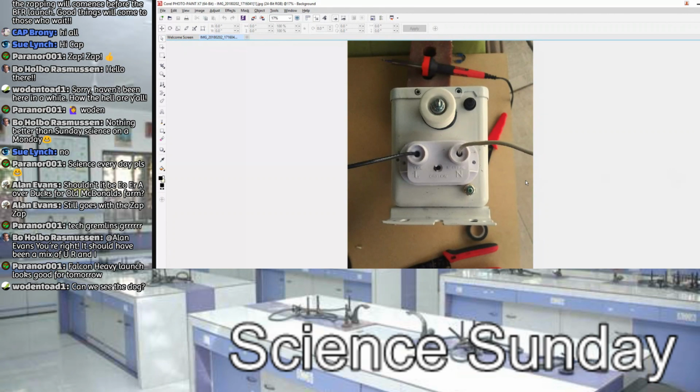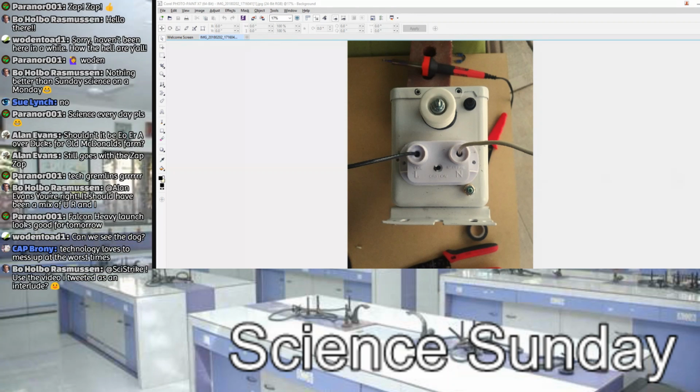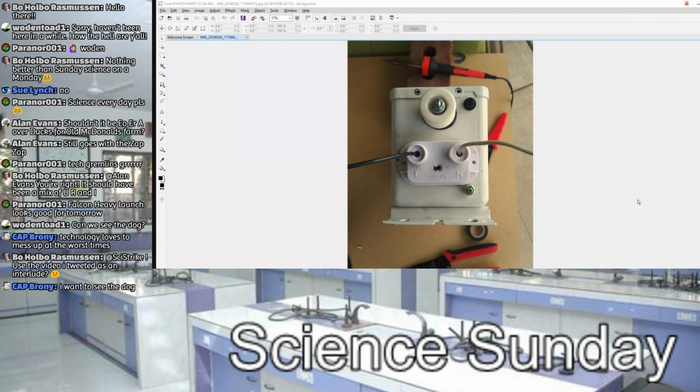So under this fancy little cap with this nice little charred thing you can see there is the ground fault interrupt circuit that neon sign transformers kind of have to be built with these days. And you can see from the char, I blew up the LED with a little bit of a feedback surge, so I went ahead and pulled that cover off, pulled the old terminals out, and pretty much depotted that entire side, which the electronics are all encased inside of an epoxy junk. So you have to drill it all out and bust it all apart, and finally got back to the actual lines going to the center coil.